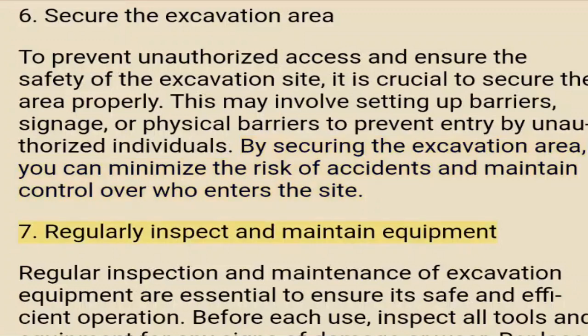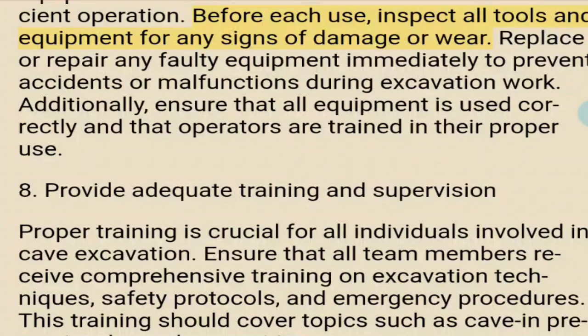7. Regularly inspect and maintain equipment. Regular inspection and maintenance of excavation equipment are essential to ensure its safe and efficient operation. Before each use, inspect all tools and equipment for any signs of damage or wear. Replace or repair any faulty equipment immediately to prevent accidents or malfunctions during excavation work. Additionally, ensure that all equipment is used correctly and that operators are trained in their proper use.